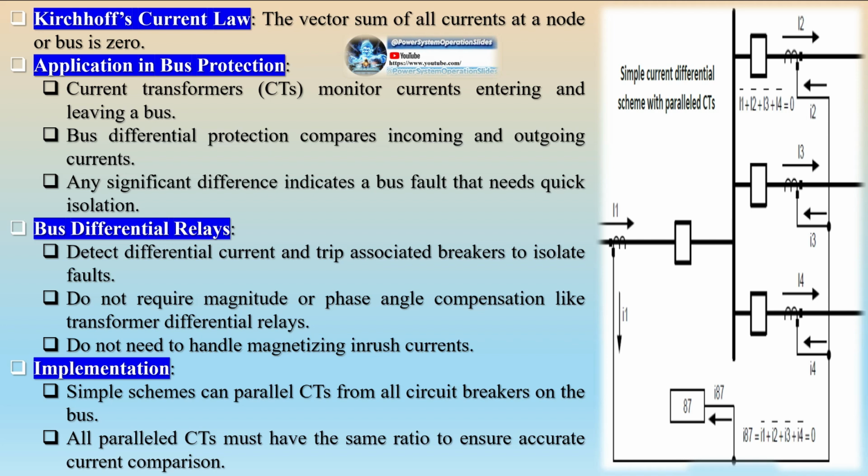Special busbar arrangements, components and their protection. Here are the key points to remember. End fault protection. This functionality is crucial for protecting zones located between a circuit breaker and a current transformer when the CB is open. It aims to handle small zone faults that the busbar protection (BBP) cannot clear on its own. This protection sends a trip signal to the line distance protection at the remote end to eliminate the remaining fault.